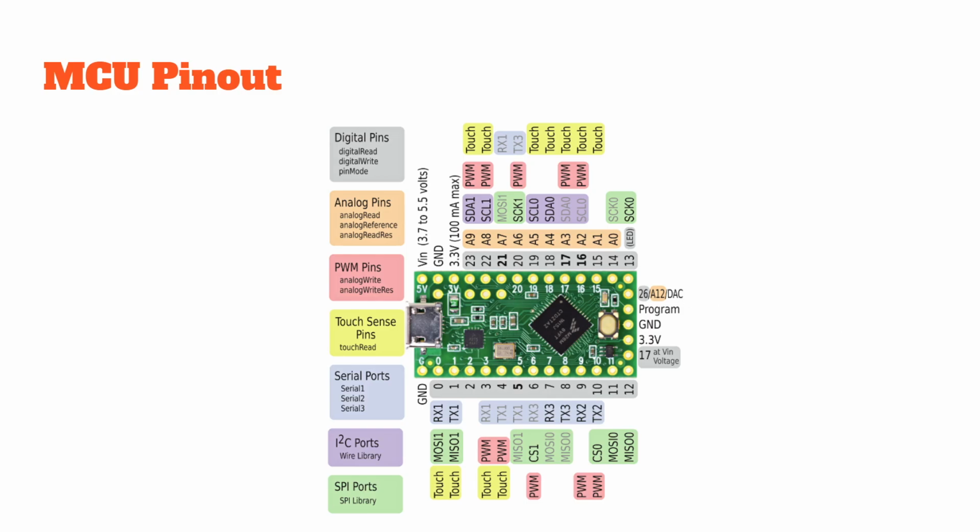So this is called a pinout diagram. It tells you what each of the pins do. Along the board, it'll tell you what number the pin is for some of these: 0, 1, 2, 3, and so on. These gray blocks on the side tell you that those pins are digital pins. A digital pin can output a 0 or a 1, with 1 being yes, there is voltage there, and 0 being no, there's no voltage there. And it'll be able to tell.